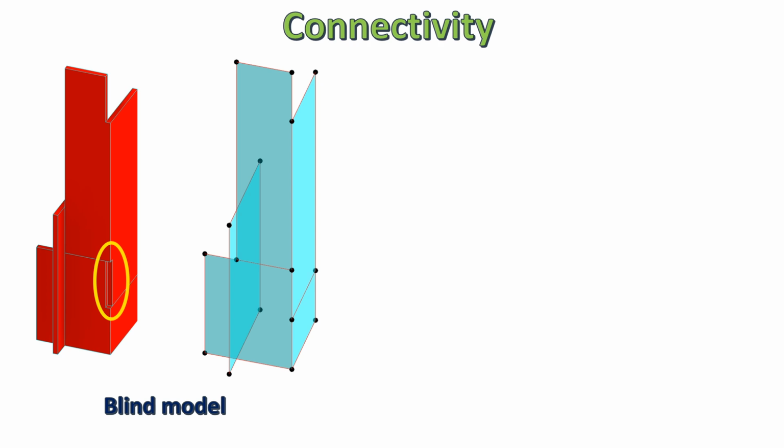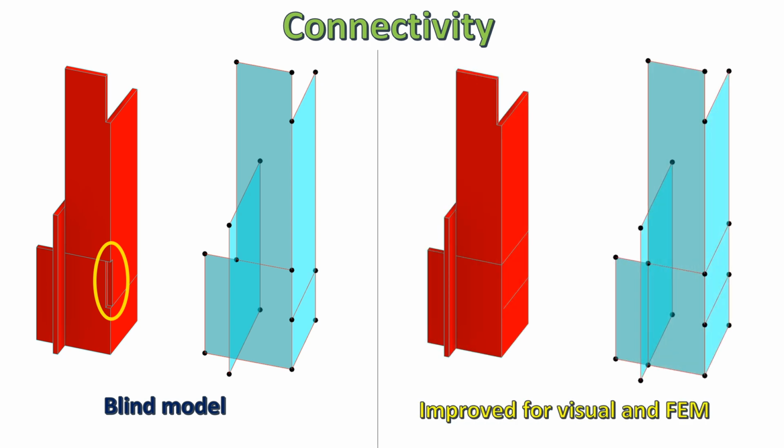The model could be improved visually by splitting wall panels so that both panels connected to each other have the same base or top constraints. Although I personally prefer the non-split wall, it is necessary to split at this particular spot. Another issue is the unconnected shell element. It could also be fixed by splitting the wall panel so that the shell elements are connected.